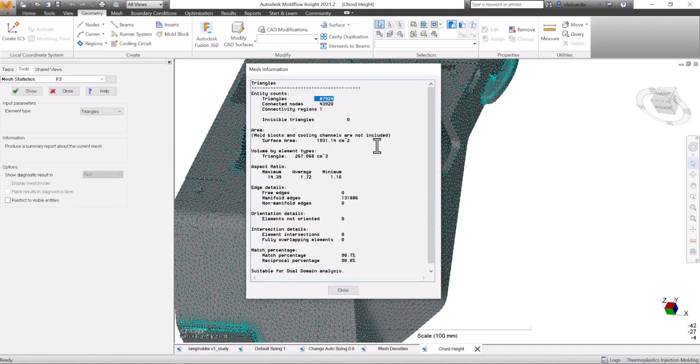So I would recommend using the chord angle only when there are small details that need to be captured and you have completely gotten rid of the small radius in the model. Otherwise, if you use it for a model with a lot of radii and curves in it, it's just going to create a lot of elements without significantly bumping up the mesh match percentage. And further, it will enhance it for the 3D mesh as well.